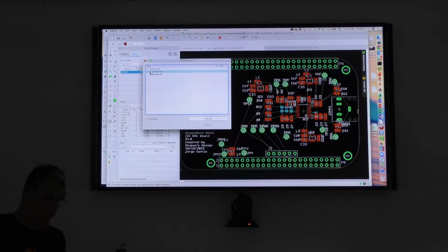That's a long-term customer complaint that this hasn't been done before in the design check. So in older versions you had to run a design check. If you have no errors in the design rules, you have to do a rat's nest command to check if there are errors left.